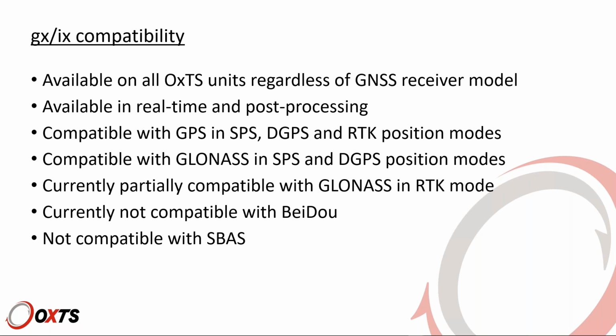It is compatible with GPS satellites in all modes: SPS, DGPS, and RTK. It is compatible with GLONASS satellites in SPS and DGPS, and it is partially compatible with GLONASS in RTK mode. Partially means it will depend on the type of receiver that you have on the base station end, the base station that is providing differential corrections required for RTK mode. That needs to be compatible with the receiver installed on the unit.